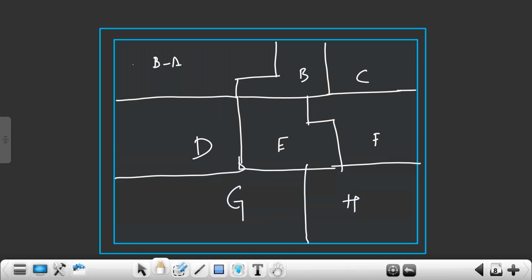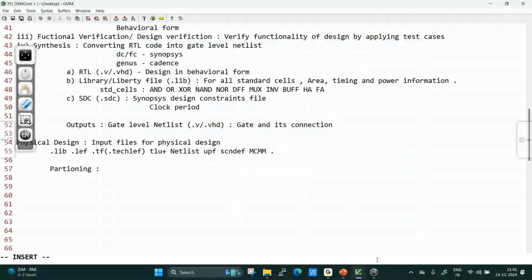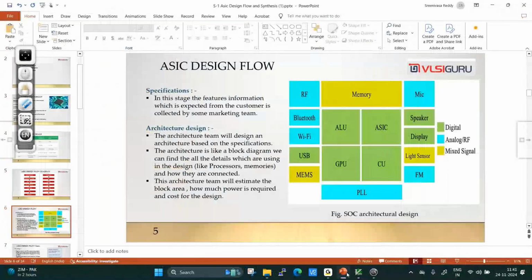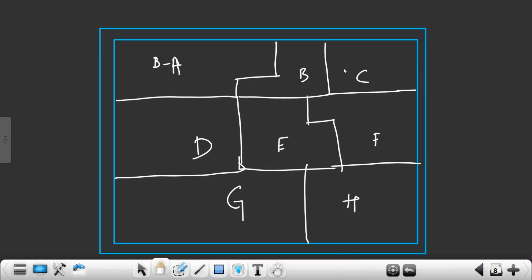So we engineers first work on block level physical design. We do physical design of each block first. Each portion of Verilog code will be given. The entire full chip is made up of this many blocks. My RTL engineer will write a Verilog program for each block, and you will be doing physical design for each block. The shape of blocks may vary. One block is rectangular, one is square, one is L shaped, one is inverted L shaped.